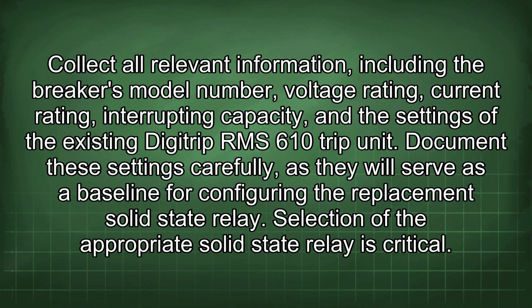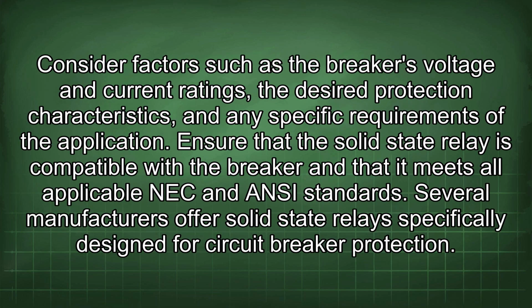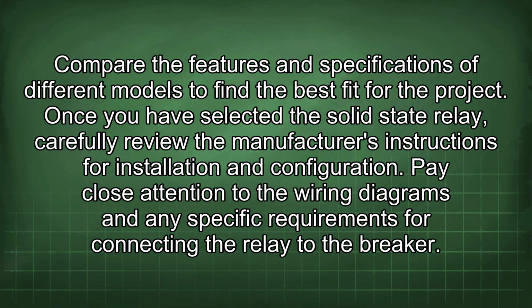Selection of the appropriate solid-state relay is critical. Consider factors such as the breaker's voltage and current ratings, the desired protection characteristics, and any specific requirements of the application. Ensure that the solid-state relay is compatible with the breaker and that it meets all applicable NEC and ANSI standards. Several manufacturers offer solid-state relays specifically designed for circuit breaker protection. Compare the features and specifications of different models to find the best fit for the project.